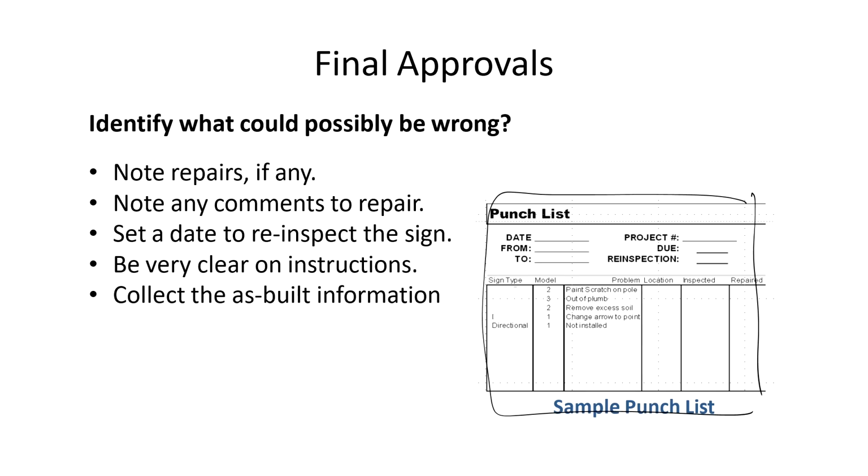Additionally, we have to gather as-built information to document the current state of the signages. This will assure that the final inspection is comprehensive and helps to maintain the quality and integrity of the signage installation process. The punch list is the document which is prepared during the inspection to record the defects, issues and corrections needed.